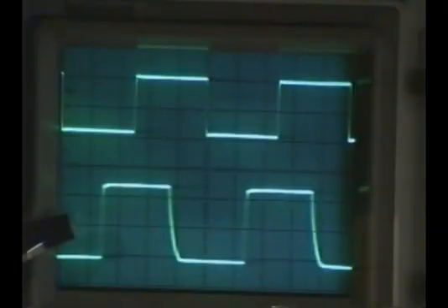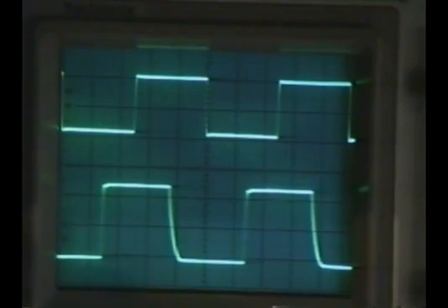Maybe if you go down to the oscilloscope, so we'll look for our... There we go. There it is. Okay. Refocus. And so let me explain what you're seeing here. The bottom trace here is the output of the VCO in the PLL. The top trace is the input, which we are putting in through the oscillator here, and I can vary the frequency. What you can see right now is that they are locked.